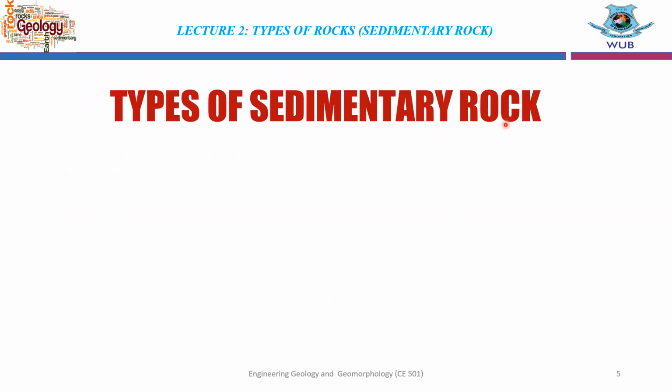Types of sedimentary rock. Okay, now we're going to the types of sedimentary rock: clastic rock and non-clastic rock. Clastic rocks are composed of fragments or clasts of pre-existing minerals and rock. A clast is a fragment of geological detritus, or chunks and smaller grains of rock broken off other rocks by physical weathering. Geologists and civil engineers use the term clastic with reference to sedimentary rock as well as to particles in sediment transport, whether in suspension or as bed load, or in sediment deposition.